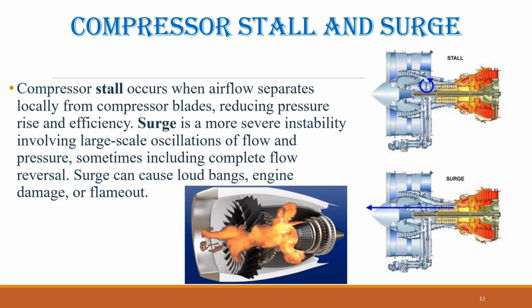Compressor stall and surge. Compressor stall occurs when airflow separates locally from compressor blades, reducing pressure rise and efficiency. Surge is a more severe instability involving large-scale oscillations of flow and pressure, sometimes including complete flow reversal. Surge can cause loud bangs, engine damage, or flameout.